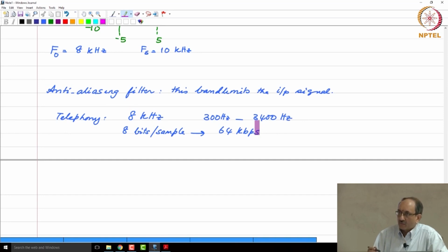When you try to say some letters as abbreviations, you will have trouble at the other end unless you clarify what it is, and that is why S as in Sam, F as in father is needed, because those sounds cannot be distinguished clearly at the other end, and that is because of this anti-aliasing filter that is cutting out high frequency components.